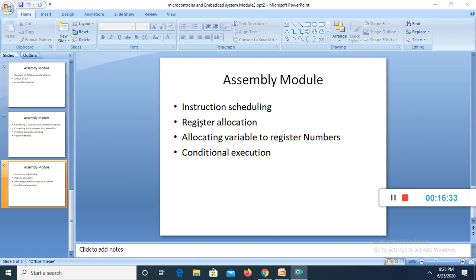The stack should be 8 byte aligned. We can use the following templates for optimizing an assembly routine requiring many registers. To keep the stack 8 byte aligned, we need to stack R12. We need not stack R12 if your routine does not call other ATPCS routines.